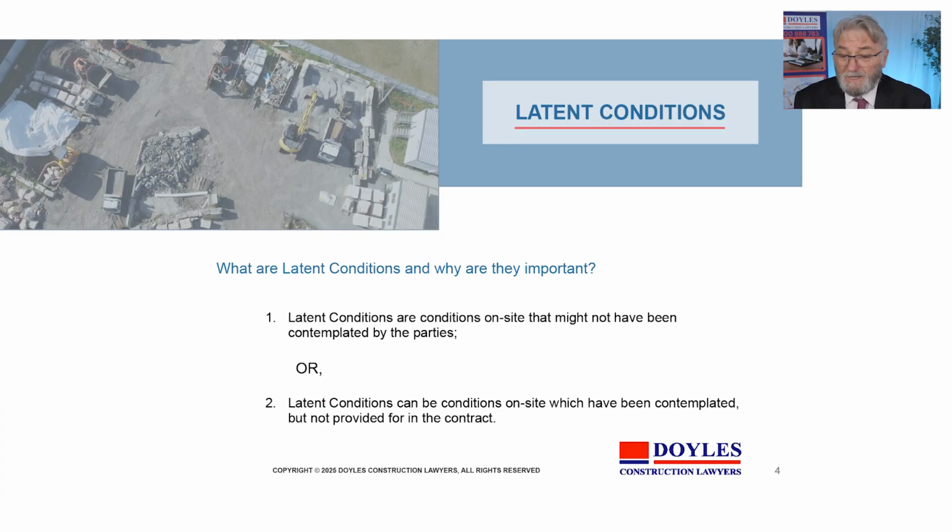What is a latent condition? Why are they important? A condition usually on site that has not been contemplated by the parties. So the big issue is that if they haven't been contemplated, they haven't been planned for. If they haven't been planned for, they're uncertain, unlimited necessarily in extent, and likely to be a matter of contention between the parties as to who pays. The concern is that if the parties start fighting over the latent condition and they're not aware of who's paying, then the management on the cost will be disrupted and unmanaged.